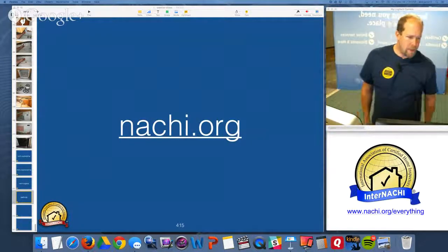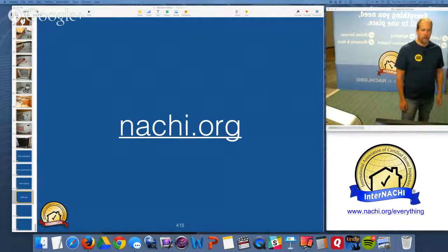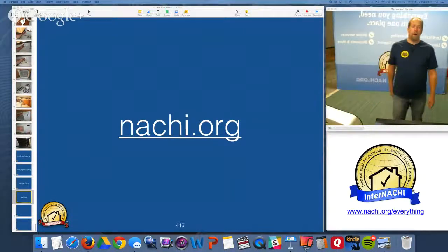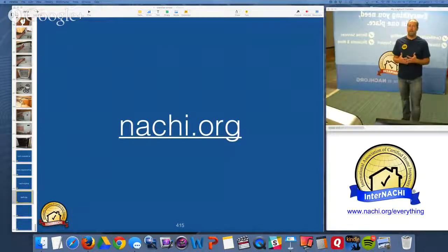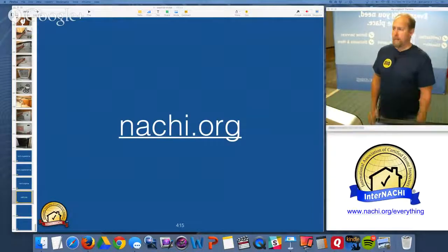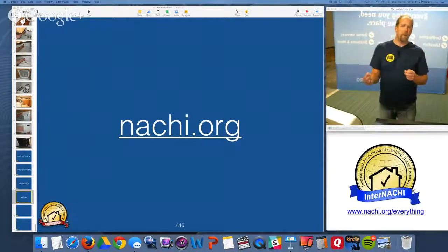Greg again. Ben, do you test receptacles for AFCI and GFCI breakers from within the home using your tester? Yes, I do. But I'm really careful because nowadays, I learned my lesson. I turned off some bedroom receptacles and there was a computer plugged in and that wasn't good. So I make sure that I'm more careful with AFCIs than I am with GFCIs.